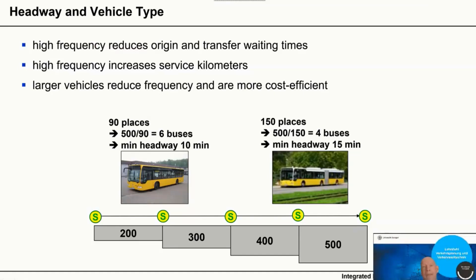And whenever you have transfers, if you have a system like a rail system where you operate a train every hour, you really need to take care of the transfers. If you have an urban system where buses or undergrounds run every 10 minutes or even more often, you don't need to take care of transfers. The transfer wait time will be small.